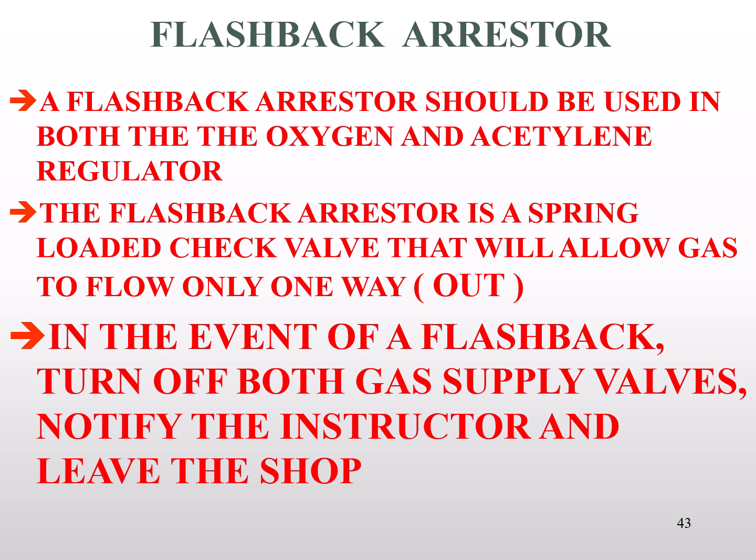The flashback arresters are there to prevent a dangerous situation from occurring, but I want to be made aware because I change those arresters if I feel like that's occurred. It's not necessarily required, but they're not very expensive, and it is a good step toward keeping the lab safe.